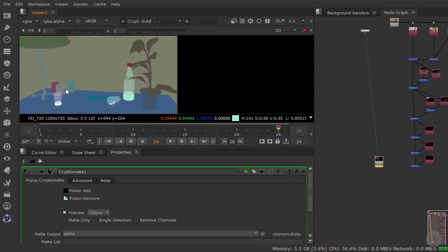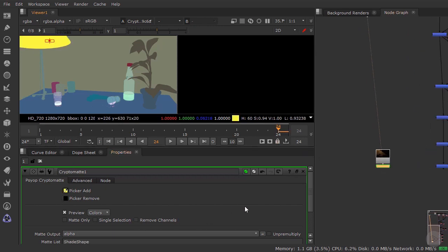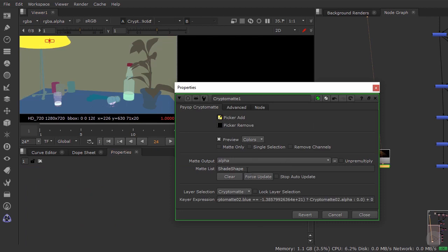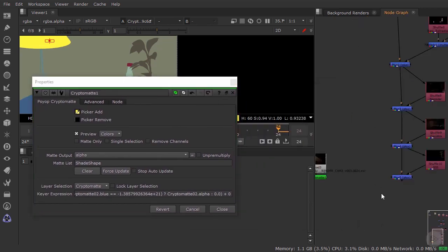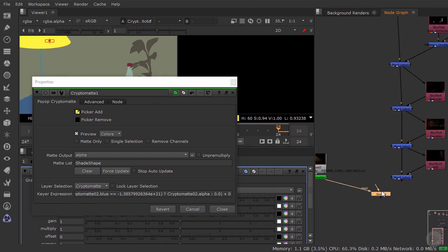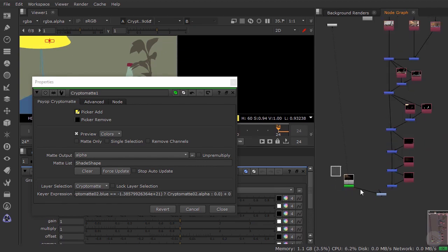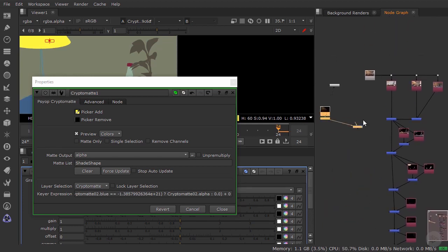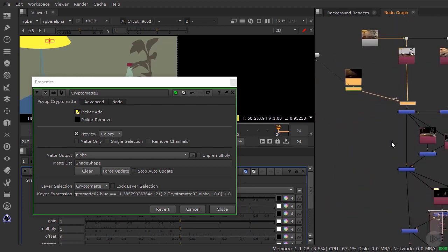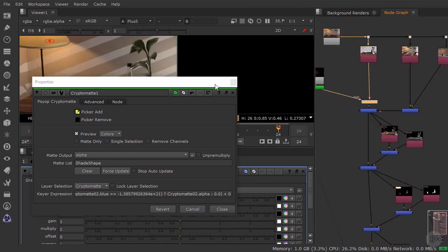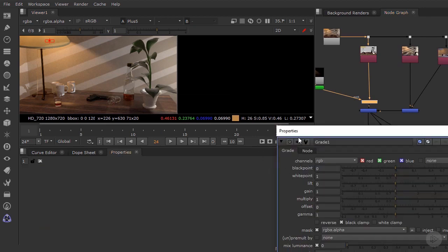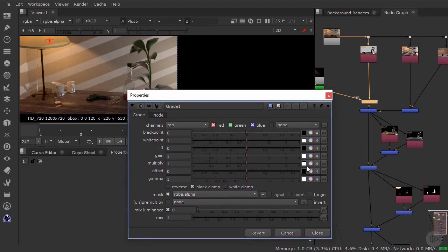do something with our lampshade. We haven't got a matte for that in our other mattes. Now, as you can see, if I bring this node out, it actually gives the name based on the name within Maya. So I've got an alpha now, and I can plug that into a grade node. And let's see, I can take this, and rather than doing it at the bottom of the tree, I'm going to do this to the diffuse. So now view the bottom, and we will change the color of our lampshade, while keeping it within the same lighting quality.